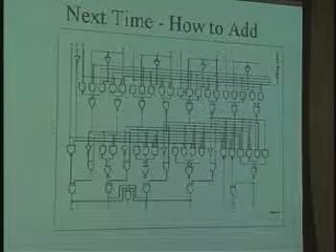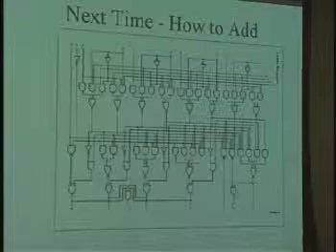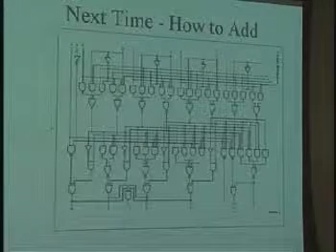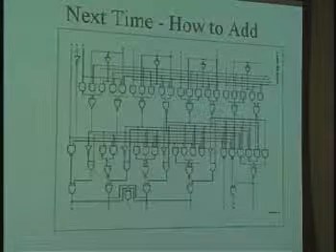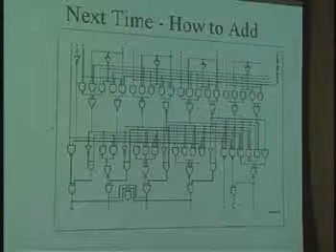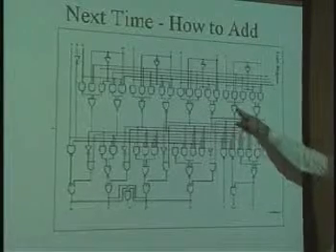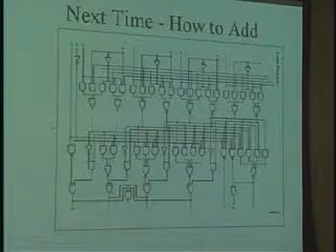The other thing we're going to do the next time is talk about a circuit that looks like this. And again, you open the hood of a car and you look at this and you say, oh my God, right? It turns out that this is a 4-bit ALU, okay? And these things over here are AND gates that do AND. These here are NOR gates, which do OR and then take the inverse of the output.